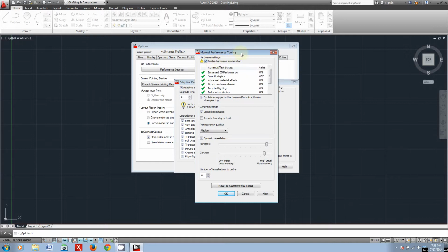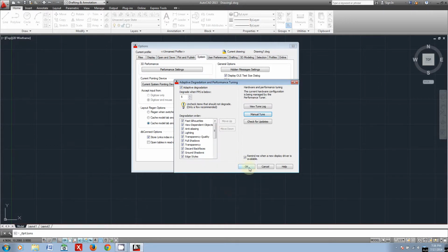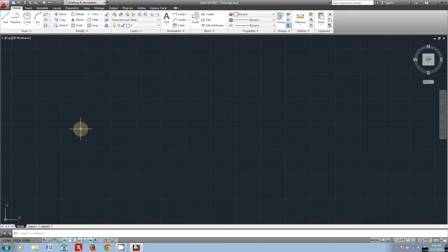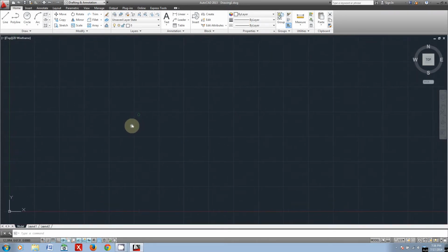Now this will allocate a little bit more energy and power from your computer to handle some of the graphics capabilities of AutoCAD. So it'll be a little bit more strenuous on your computer. You might have to plug into a power source if you're on a laptop somewhere, but it can be well worth your while to eliminate lag. So go ahead and apply these properties and you should be good to go. Now if you have more problems, there's a lot of online resources on how you can improve your AutoCAD performance, but I won't go over these. You can look those up.